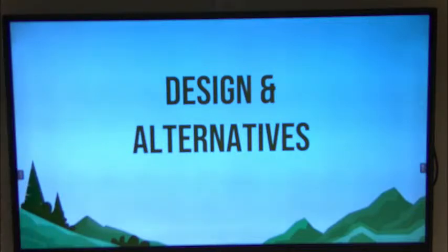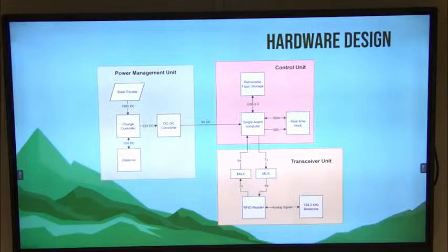Thank you, Ivan. So for hardware, we designed a 3-unit system. We firstly have the power management unit, which contains the solar panels for a total of 400 watts. Then we pass that power to the charge controller, which then charges the battery and powers the load when there is sunlight. And when there isn't sunlight, then we have the batteries as a backup for the system to continue during the duration of the deployment.